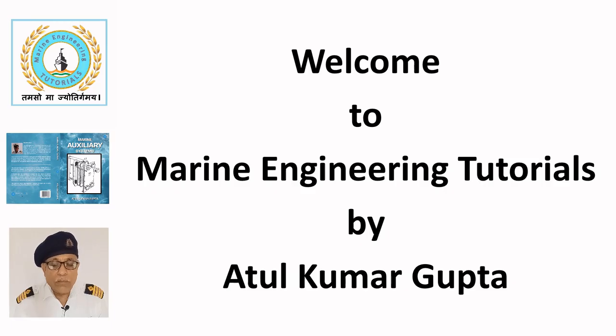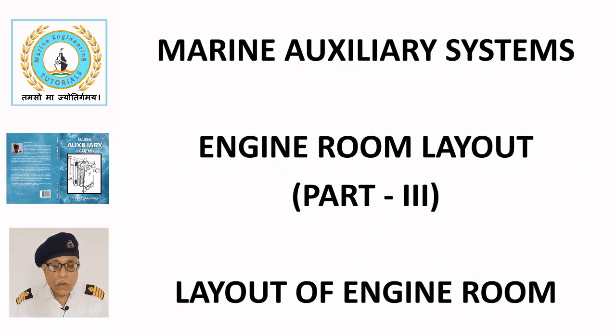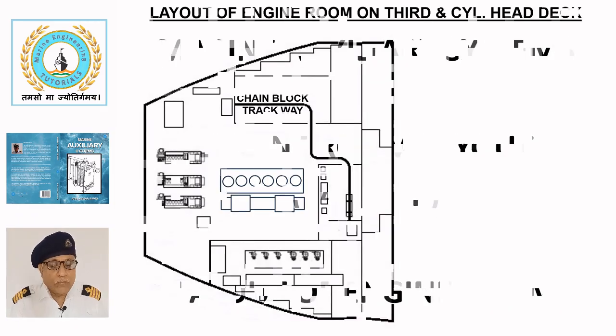Currently we are studying Marine Auxiliary Systems. The topic for this lecture is Layout of Engine Room Part 3. We will first explore the layout of machinery on third deck of engine room of an oil tanker. Next, we will examine the layout of machinery in engine room at second deck. Let us now go through each of these topics one by one in the following slides.